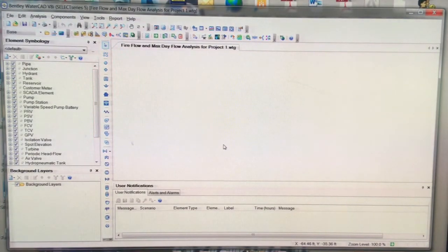Now again, single family homes for Orange County Utilities is going to be 350 gallons per day on average for each single family home. So you add up your number of homes, say it's 100 homes, so that'd be 100 times 350, and then you would divide that, because you want to get down to gallons per minute, so you just do all those calculations.